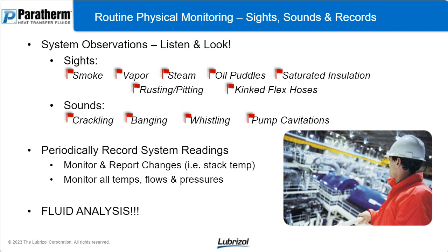Do you see any evidence of leaks, oil puddles or staining or drips or black gunk being built up around fittings? When a system's at full temperature, things expand. You might not always see the leaks, but look for evidence of leaks, so puddles, stains, accumulations. If you have insulation that's saturated and wet, that means there's a leak, and that's a big problem. It's a fire hazard if you have insulation saturated with hot oil.